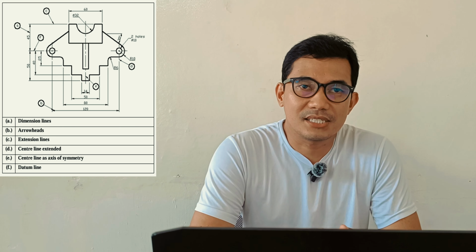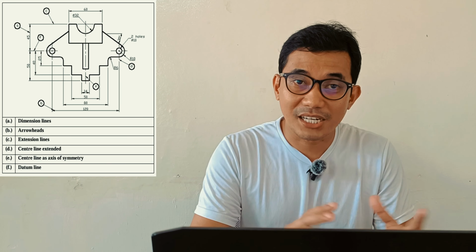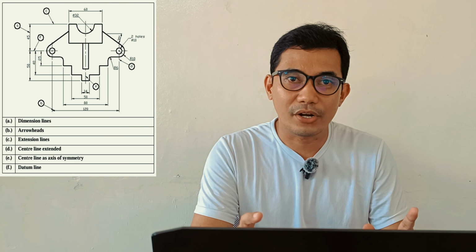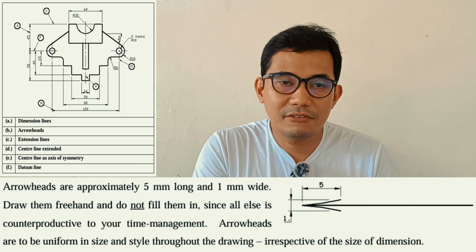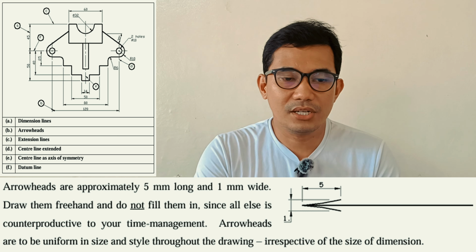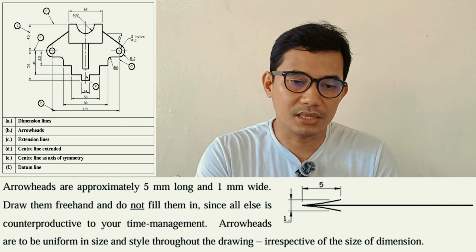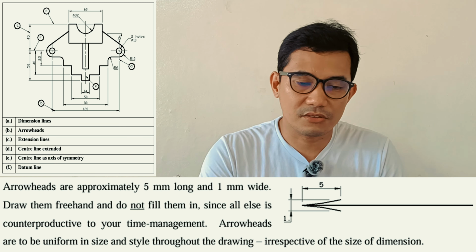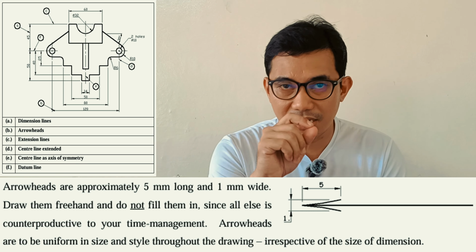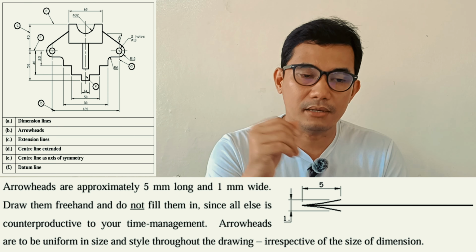Now next, arrowheads. Again, mo ni ang common nga ginagamit sa pag-drawing. Magbutang na kayong dimension, the end-to-end of your dimension line is the arrow or the arrowhead. Arrowheads are approximately 5 mm long and 1 mm wide. Draw them freehand and do not fill them in, since all else is counterproductive to your time management. Arrowheads are to be uniform in size throughout the drawing, irrespective of the size of dimension. So, pwede rin mo i-freehand ang imong arrow as long as approximately it is 5 mm and 1 mm.